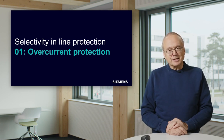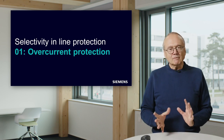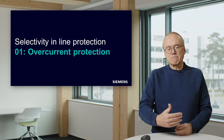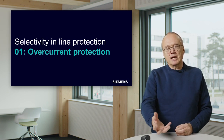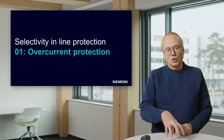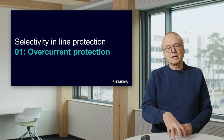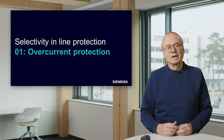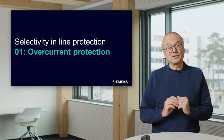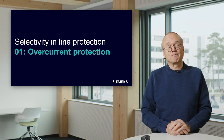If we look at distance protection, at first glance it looks also pretty simple, because distance protection measures the impedance, and by this it can decide, is the short circuit on the own line or cable, or is it on the next line? But we will see later on, it's not that easy. We also have to look into that.